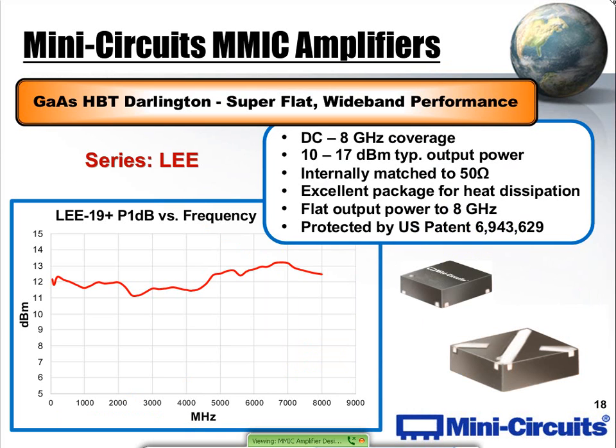And now I just wanted to spend the last few minutes of the presentation going over a couple of real-life examples of what we just talked about, and I'll touch very briefly on them. This is our Lee series amplifiers, and we talked earlier about the Darlington configuration, how that configuration is extremely adaptive for wideband, flat frequency performance devices. This is a modified QFN package that we make. It's a plastic encapsulated solution with a very low inductive lead frame, so the lead frame is adding very few parasitics to the chip.